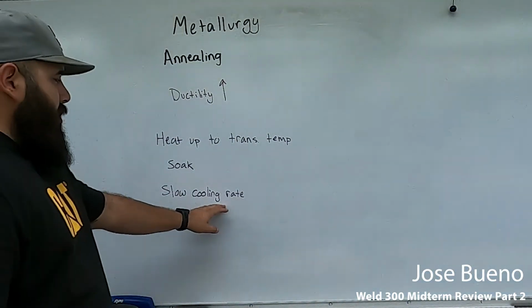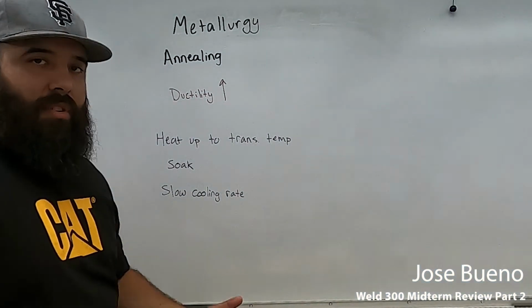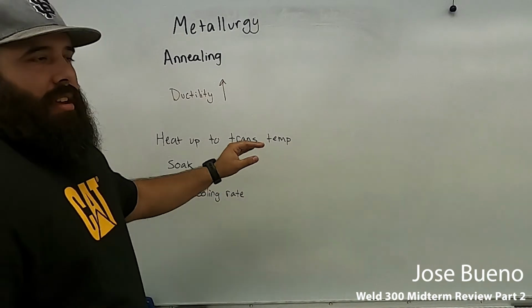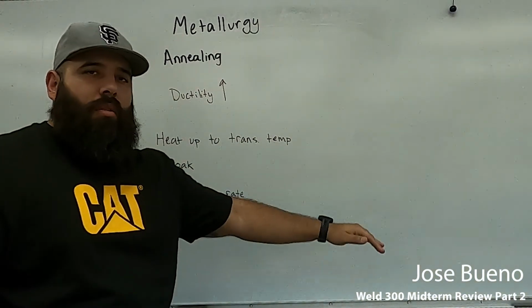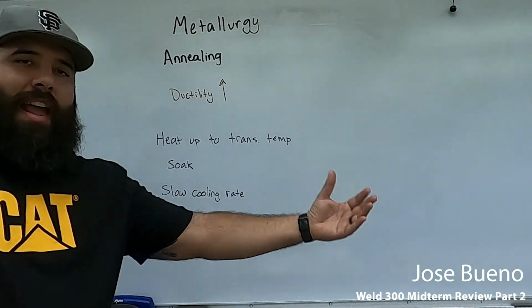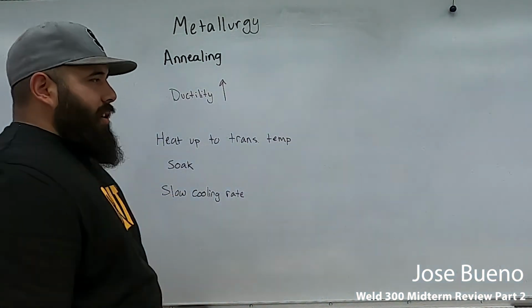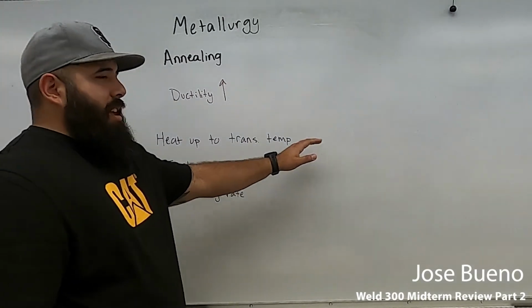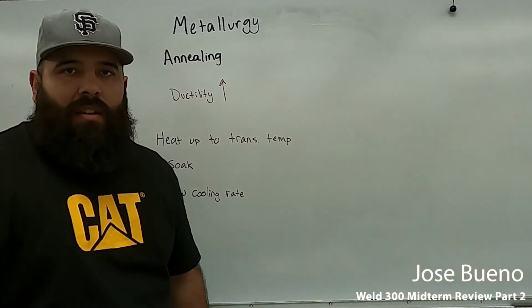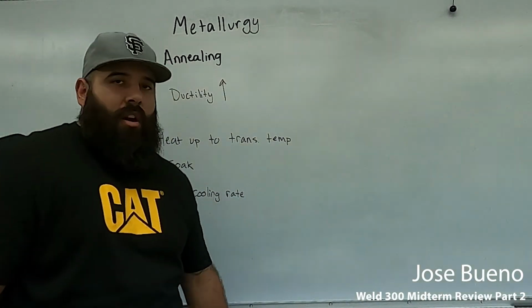What we're doing by decreasing the rate of cooling is actually taking away a little bit of heat over a prolonged period of time to really drag out that cooling time. So depending on the temperature, maybe an hour goes by and we reduce the temperature by 100 degrees. The next hour we drop it by another 100.